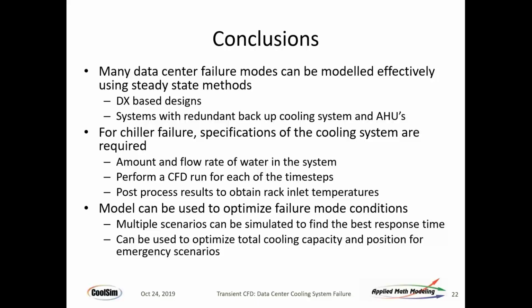Now, with respect to the other conditions where you have a chiller fail, then you can go ahead and just run it that way. And what these models can do for you is allow you to optimize those conditions. In other words, in a failure mode condition, what is the best thing I can do? In some cases, what I've seen people do is open the doors of the data center and put in portable fans or portable cooling units. That's okay if it's not contained. If it's contained, you might have trouble with that approach, particularly if it's cold out. That's not going to help you.